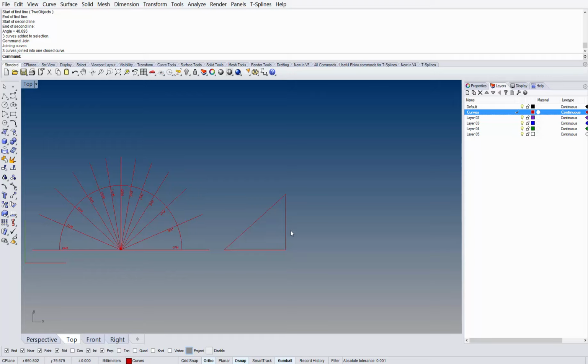You know, let's actually do this backwards, because the most important angle is the 40.71. So let's draw another line like this. Let's draw another line, and starting from here, let's do 150 millimeters. Left click and then right click to end it. And I'm going to just move it over a little bit. That was just my starting snap point.